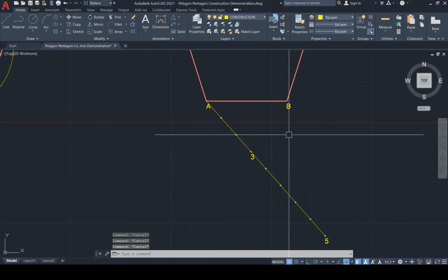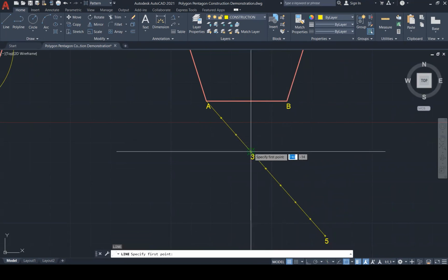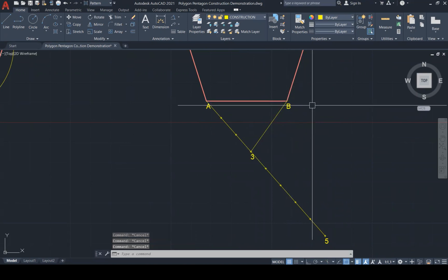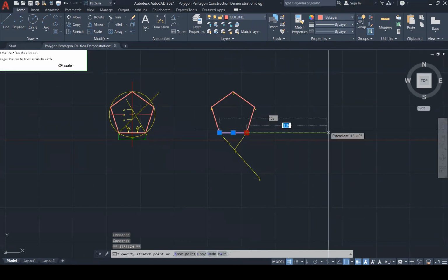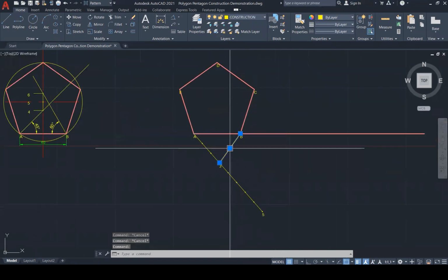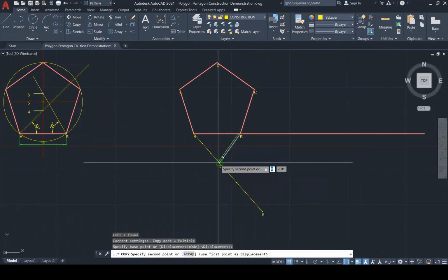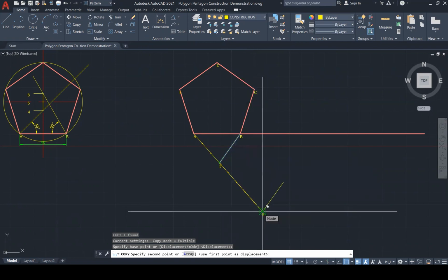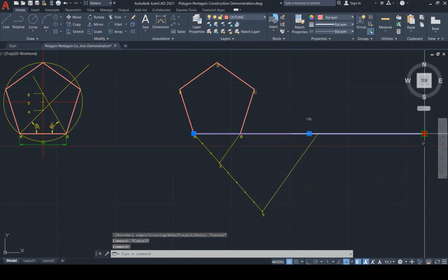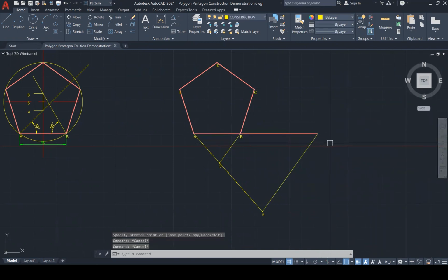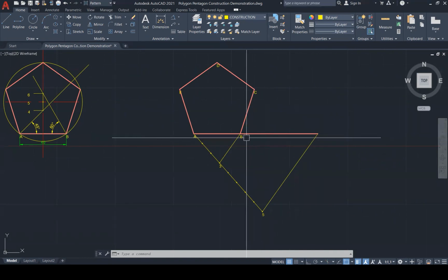Now we need to make the shape AB3. So I'm going to attach 3 to B. What does that mean? Is now the shape is at 3. Or at least the distance AB is at 3. Let us now extend this line outward to some random distance. And I'm going to copy 3 and bring it down, copy the line that is at 3 and bring it down to 5 and snap it into this node point and then extend this line all the way to here. So it comes all the way to here, so I can drag that back here because that's the full length that I need, right? That is now our new B. This is now B that is at 5. So this will be called B prime.